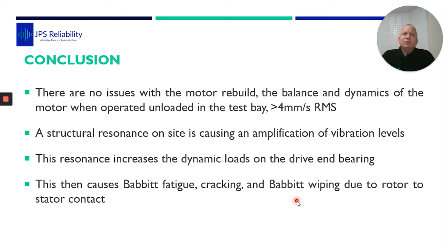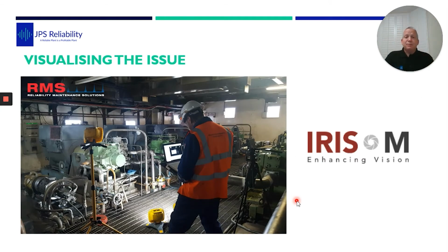Now, this is about 2017, so we've been going around for a couple of months. And at this time, I was chatting to Keith at RMS, and they were using motion amplification. So this has just come in and they're starting to use it and find their feet with it. So I gave Dean a call, got hold of Stu and Keith. Keith came down to site, and with Keith we tested the motor. So I had all my bump test data, all my vibration data. I knew that that motor was twisted. I knew the frequencies it was running at.